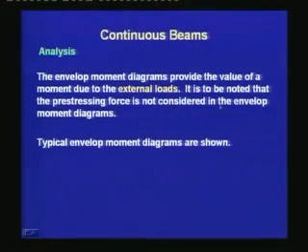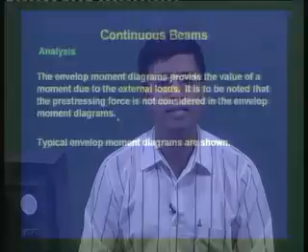The envelope moment diagrams provide the value of a moment due to the external loads. It is to be noted that the prestressing force is not considered in the envelope moment diagrams. When we are talking of the structural analysis due to the external loads, we are not considering the effect of the prestressing force. The envelope moment diagram gives the moments just due to the external loads. The effect of prestressing force has not been considered yet. Now, typical envelope moment diagrams are shown in the following sketches.